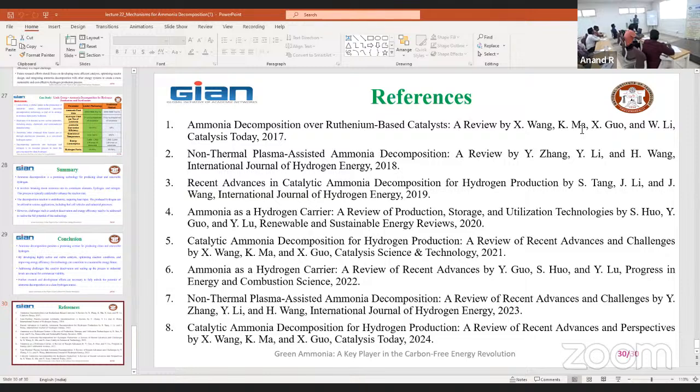Then for the same number of hours we tried with biodiesel, and we proved that there is no need for any replacement of the material when they go for biodiesel. But some components need to be coated against erosion, particularly those with rubber as well as the copper components. We use copper in many places to avoid leakage. Wherever copper components are exposed, similarly even in the fuel injector and fuel pump, there are some elements associated with copper.